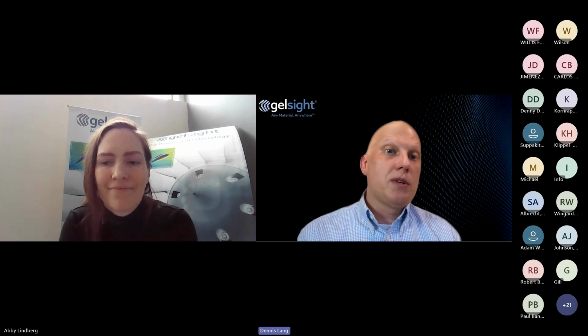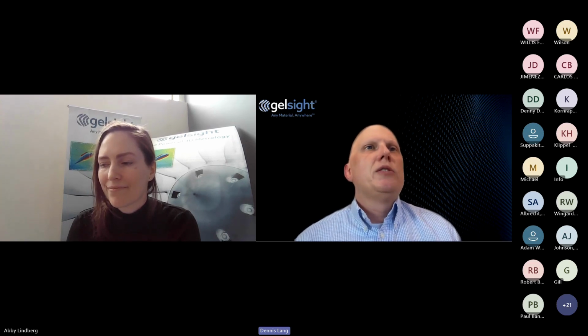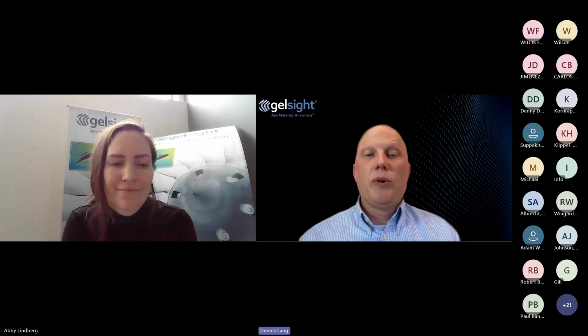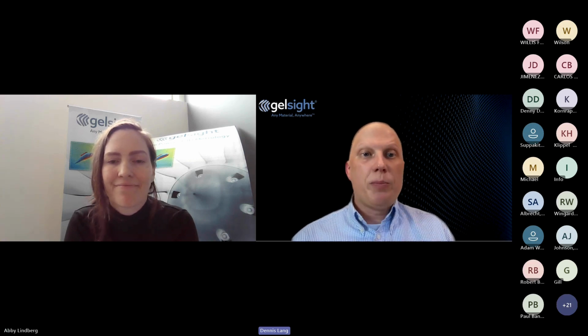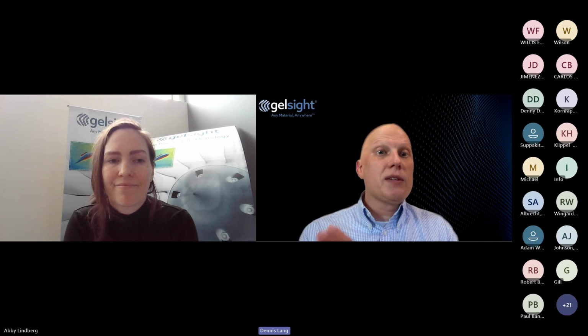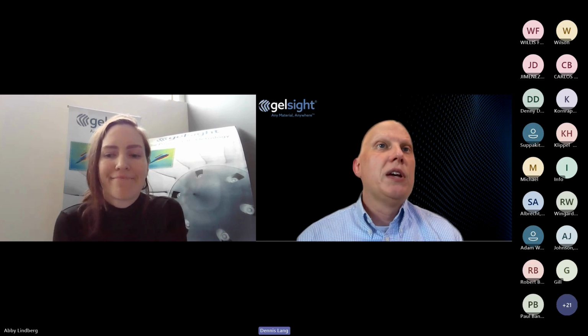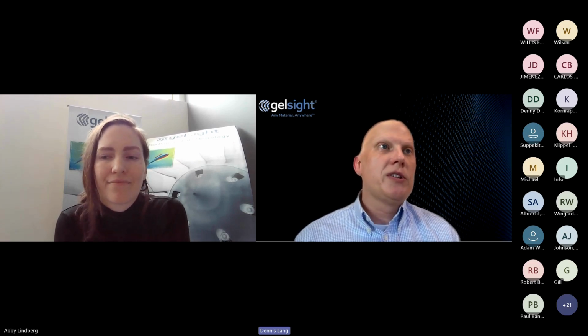You're getting quantitative decision making. This is really important, especially when you look at the typical ways of inspecting holes that are in situ or on large pieces that can't be either disassembled or taken into a laboratory environment. You're getting hard visual dimensional data. We've proven the consistency, whether you're in the depot level to the metrology lab. We have papers where customers have actually done MSA studies against very expensive desktop kind of standard systems to GelSight, and we match that in the field with our systems. So you can be very confident on your calls about part conditions, and you can present the traceable reports to back that up.